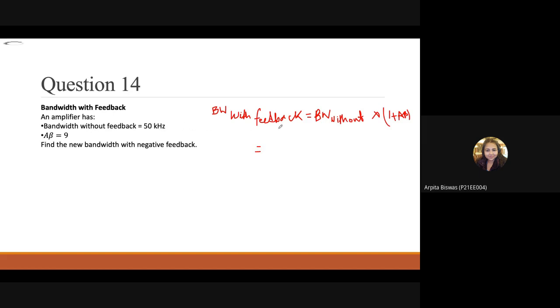Ma'am, yes. Without feedback it is 5 kilohertz, sorry, 50 kilohertz, into 1 plus A beta, 9. So 500 kilohertz.